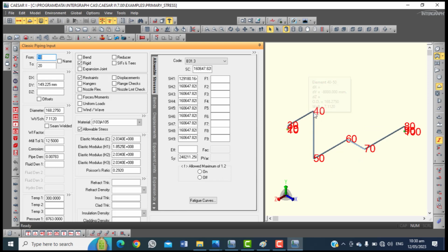If you look at this pipe, it looks very long. This is a riser, and I think it should be the longest part of this piping system. So I'm going to support this pipe at this point, since this point is trying to move downwards. I'm going to support this vertical section of the piping system here, and then place another support here, and then another support here, right?